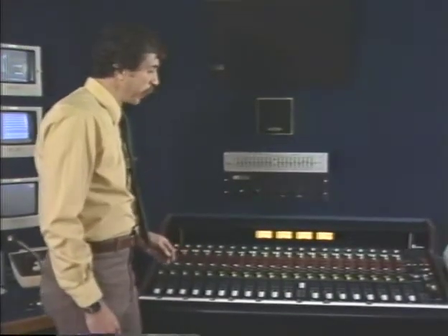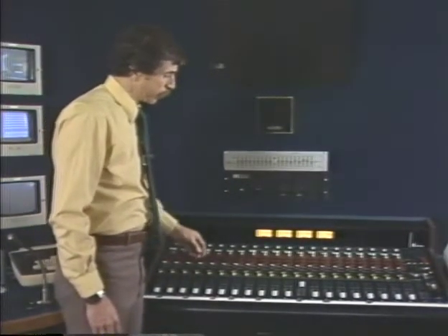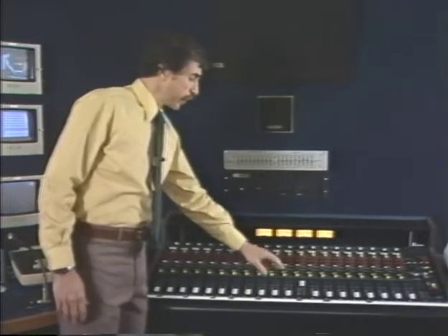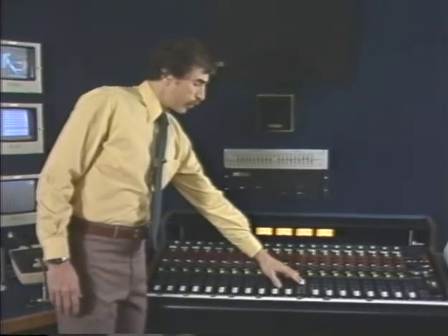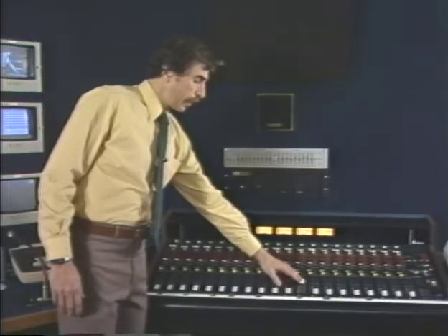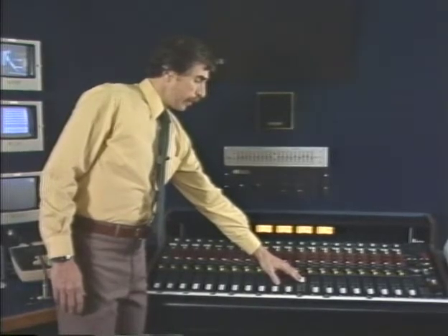Now, let's take a look at the audio master control panel. This panel has, of course, for each channel, for example the channel that we're working on, a volume control. I can turn the volume down, and I can turn the volume up. And for this particular equalizer circuit, it has a set of 3 bandpass filters and knobs which let us put in up to 12 dB gain or 12 dB attenuation in each of the bands, and also a selector switch that lets us select the center of the band.